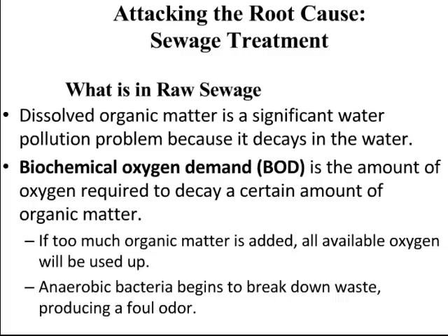Once it has no oxygen in it, the water is said to be anaerobic. Now obviously fish can't live in anaerobic, no oxygen conditions, so that will kill fish in a waterway. But it also allows the growth of anaerobic bacteria, bacteria that don't need oxygen to survive. These bacteria grow, break down the waste, produce nasty stinking odors and awful tastes, and make the water unusable in terms of drinking water. So we can't allow too much waste that would increase BOD to flow into a river.